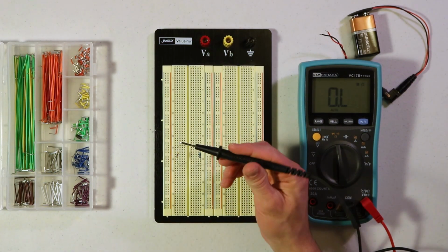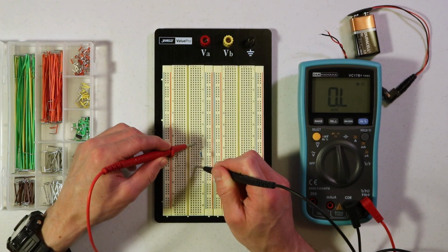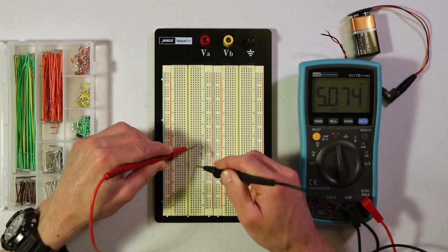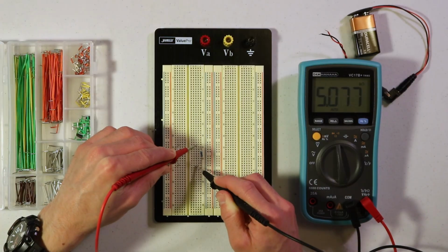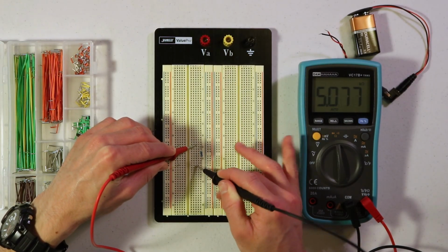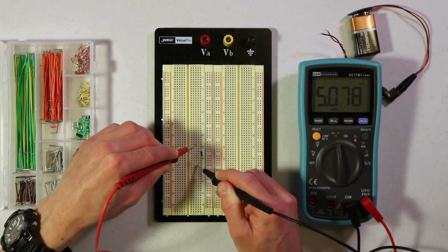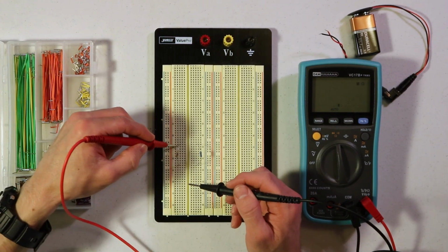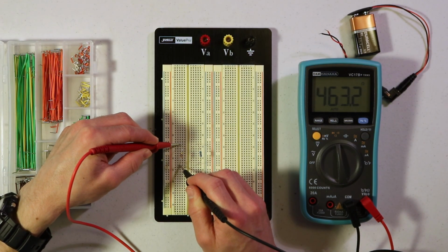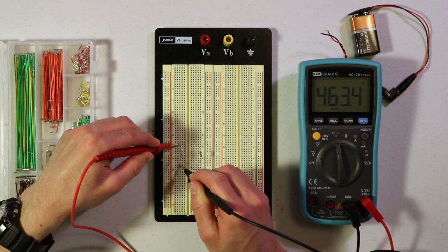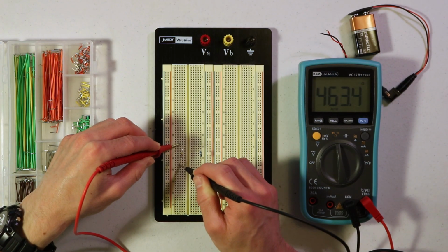then you can press the probes down into the holes like that, and it'll kind of hold itself in place. You know, it won't wiggle around. You can kind of get it fixed there in position. So just checking this right now, this one says that it's 5.077 kiloohms, which is very close to the nominal 5.1 kiloohms. And if we checked this other one here, where it's supposed to be 470, we have 463.34 ohms, so that's very close to this 470 ohms, which we predicted.